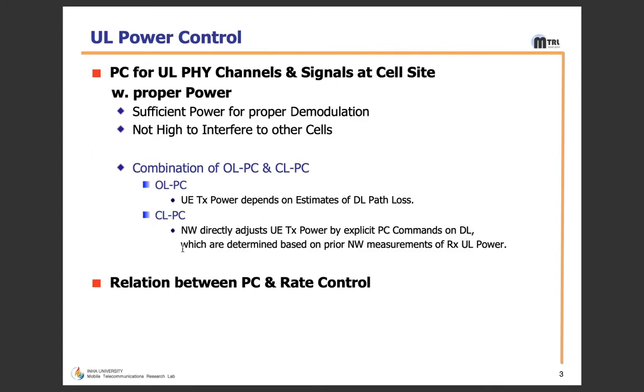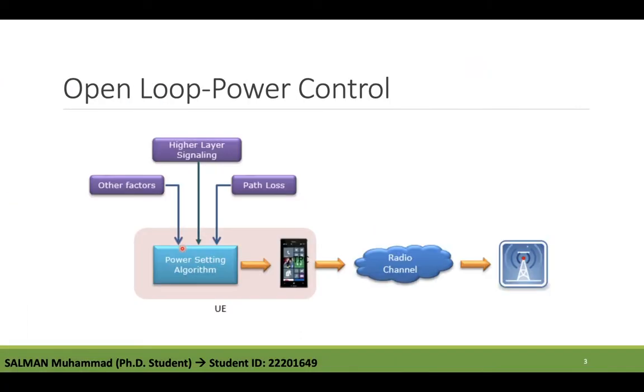For the uplink power control, let me show you first the big picture of the open loop power control and the closed loop power control. There are roughly two different power control mechanisms. One is called open loop power control and the other one is called closed loop power control. When we say open loop power control, it does not mean a loop control. It is just a one-direction control process. There is no feedback, as illustrated in this figure. Actually, a control path that does not have any feedback input is the definition of open loop in control theory.